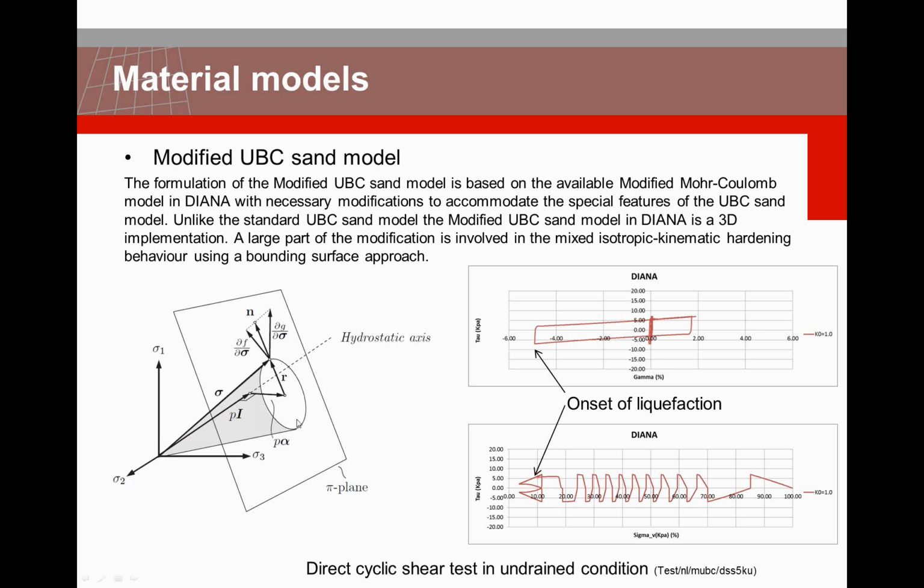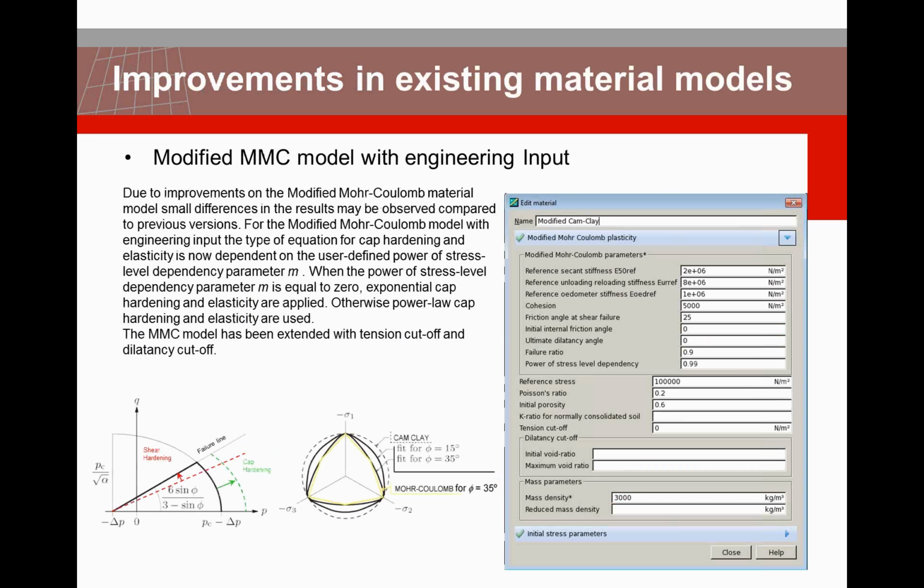It has a plastic cap also for nonlinear compression, and the hardening behavior is prepared for mixed isotropic kinematic hardening, so that we can simulate very nicely cyclic behavior up till onset of liquefaction, as is illustrated in the graphs here. But also the existing traditional models, as for example the modified Mohr-Coulomb model, have been